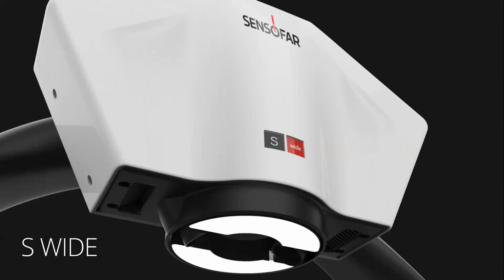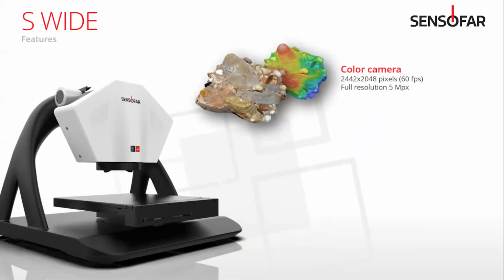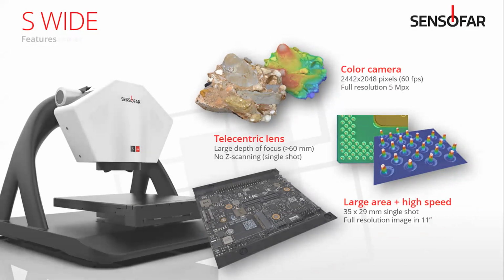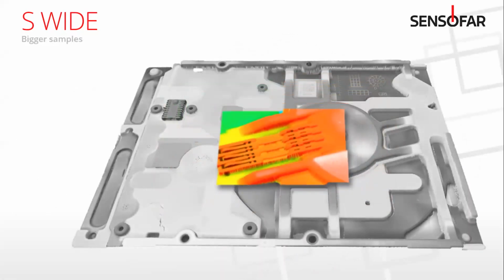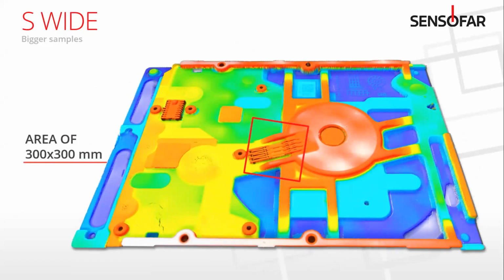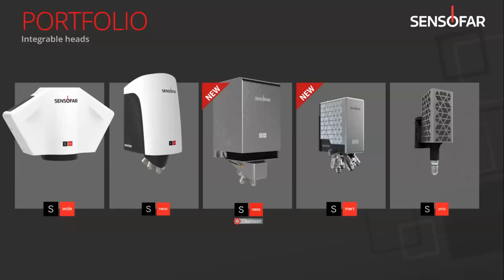And then finally, we have the S-Wide, which is kind of our fastest method of scanning. It's not going to be quite as resolute, but it captures an area of about 30 by 30 millimeters in one shot. It's got a full color camera. It's very fast, and it has a telecentric lens, which means you can get about 60 millimeters of depth of focus in one shot. Here's an example part being scanned in grayscale and then having the heat map applied to it. So a 300 by 300 millimeter part scanned fully.